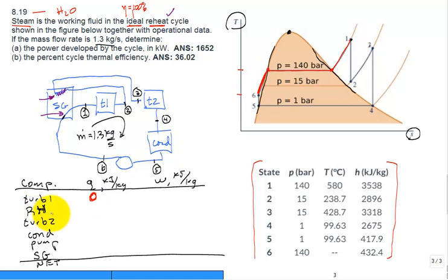All right, then you have the reheat. That has no work in the reheat, but you have heat transfer. Turbine, second turbine, no heat transfer, but yes work. Condenser, no work, but yes heat transfer. Pump, no heat transfer. And then steam generator, no work. And so I maybe should have tried to draw some lines going across to help keep those straight.